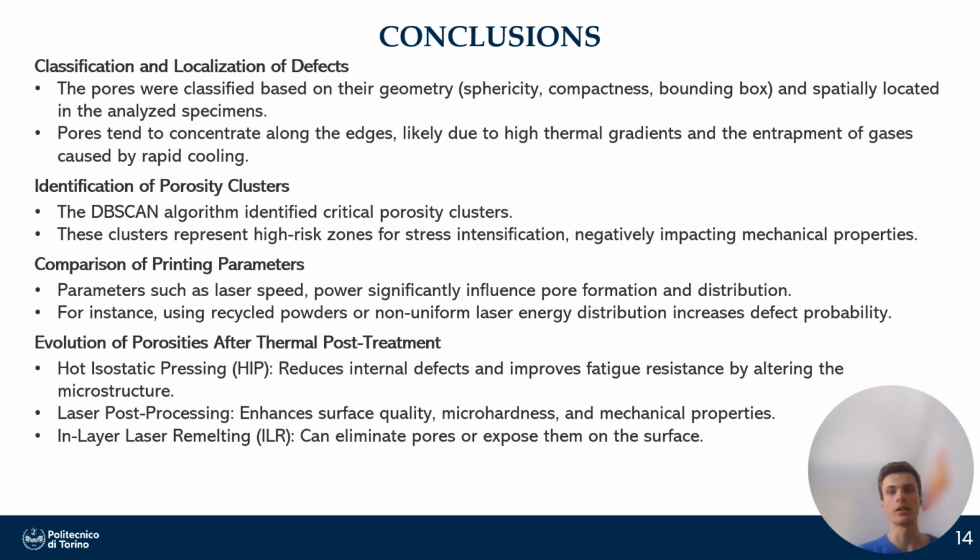We observed that they tend to concentrate along the edge, likely due to high thermal gradients and gas enrichment caused by rapid cooling. Furthermore, by leveraging the DBSCAN algorithm, we identified clusters of porosity, which are particularly critical as they represent a gray zone for stress intensification, ultimately compromising the mechanical properties of the material. This insight enabled us to compare various thermal porosity treatment techniques to determine which provide the most beneficial effect.